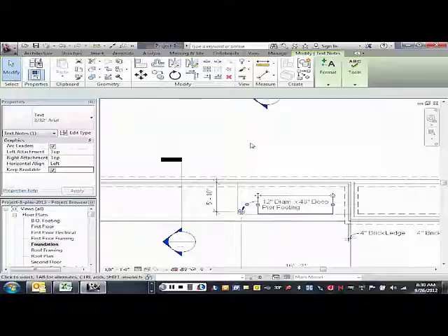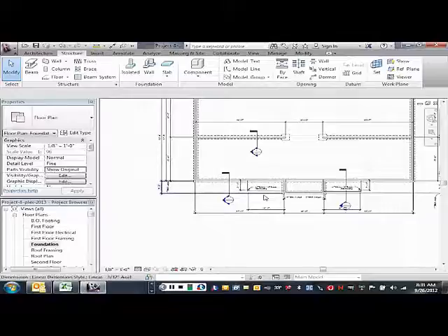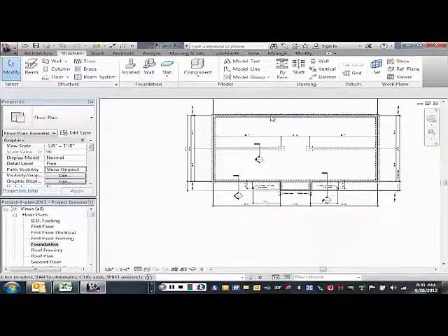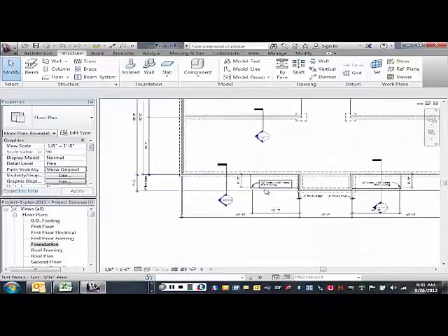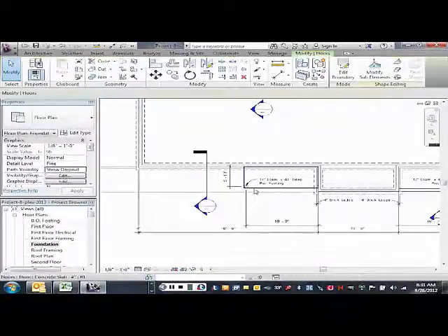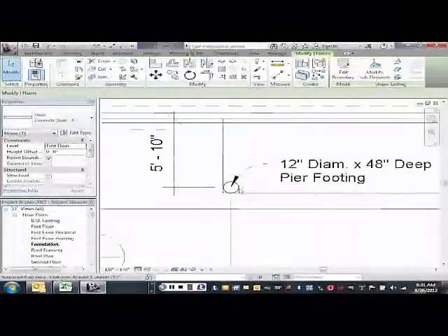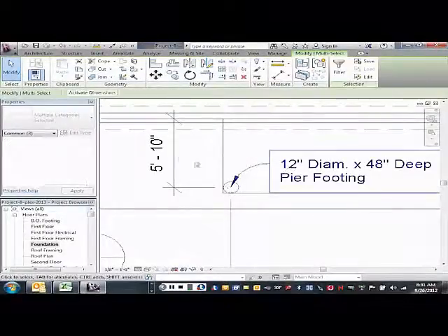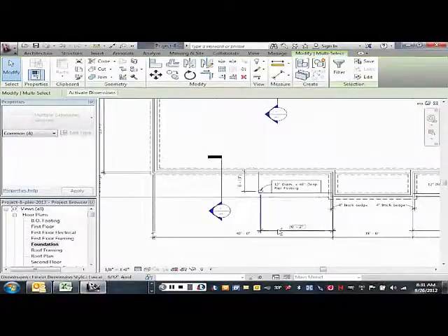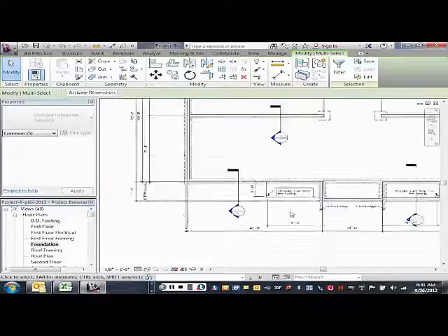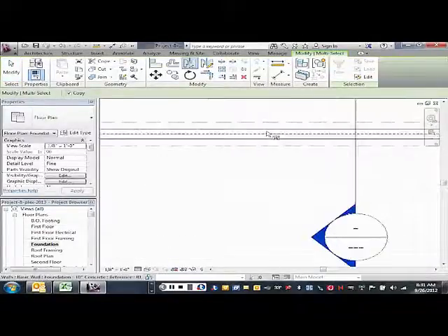Okay. So as we just discussed, I want to put this same patio on the back. Since I mirrored those units over, that unit should be exactly in the same location. So if I click on these items, hold the control key down and select that, and I can select the dimension, and I can select this dimension, and I can mirror that off the center of this wall.